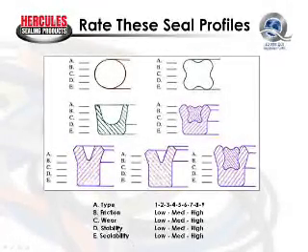What about stability? We have now improved the stability of this seal over the O-ring because now we have a square configuration instead of a round. So our sealability is going to have improved. So we have a better performing seal from the quad ring than we do from the O-ring.